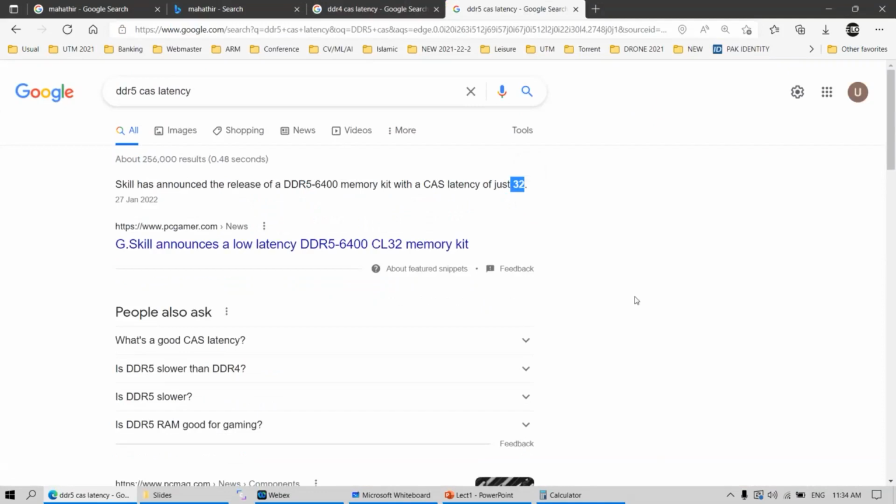So the latency in terms of clocks is not much improving, but this is half the story. Why? Because at DDR5 the clock rate is also higher. You have more clocks to spend waiting, but the clock rate is also higher.